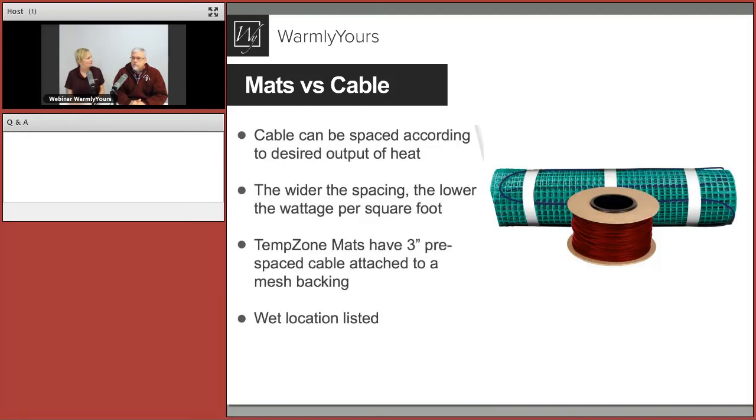The one thing that we like to make sure is that you're looking at the details in terms of the insulating factor of the cork flooring. So you really want to understand what's the R value of that cork. If it's over about 1 R value, then we would tell you that it would be less energy efficient under cork than other flooring surfaces. And you're going to see in our next few slides why. All right. The idea is to heat on top of cork, not really underneath it. Cool. So that's what you want to keep in mind. So what you want to do, Sam, is see what the R value is of the cork.